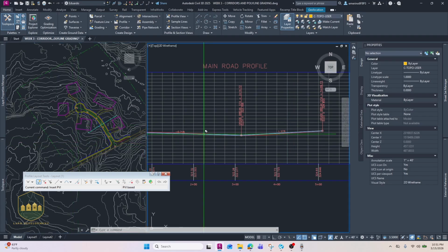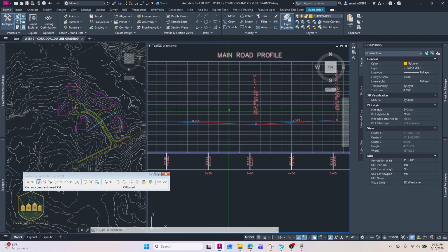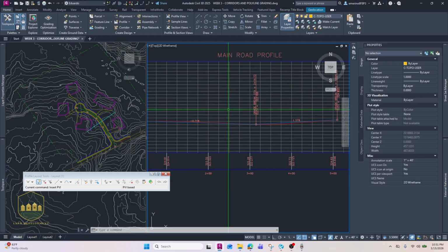And if you watch my other video, we can do a quick exercise and see how much I need to lower the road and raise the road if we are cut heavy to make sure that the earthworks are balanced. I know by doing the previous exercise that this site, if I just follow the existing road as close as I can while providing enough slope for drainage, is going to be fill heavy. And I need to lower this proposed road so we're balanced.